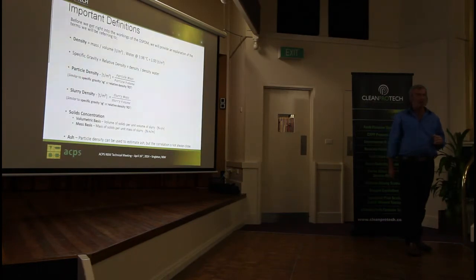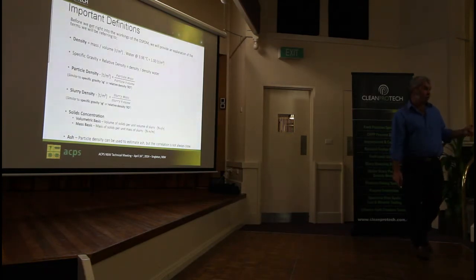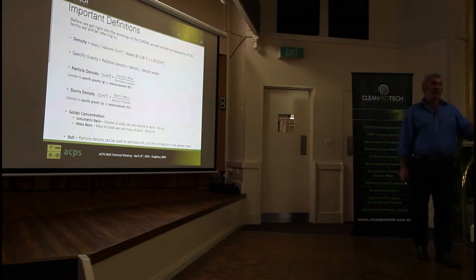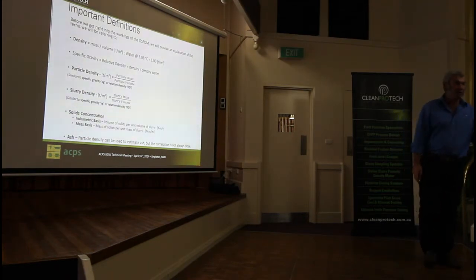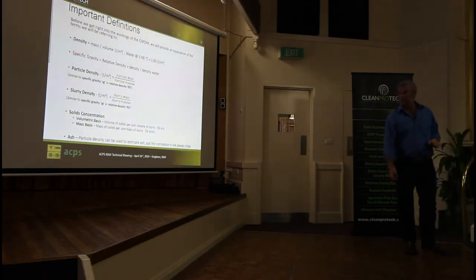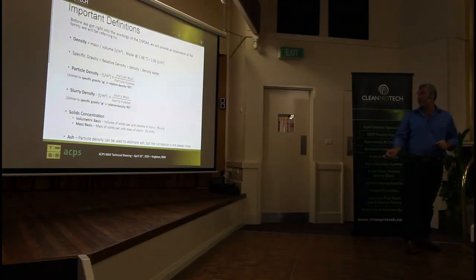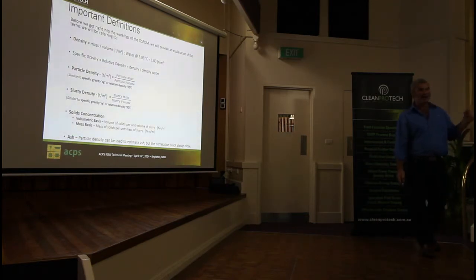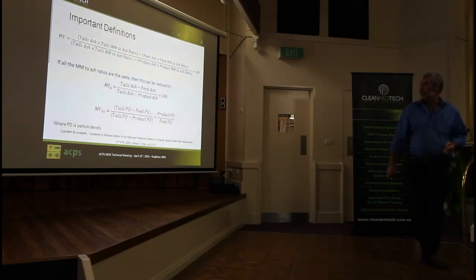And of course you've got solids concentration. Very important to remember with solids concentration, for percent solids, there are two different things, by mass and by volume. They're not the same and should not be confused in any way. Okay, ash and particle density, again, it's another story. Don't confuse them. It's interesting: particle density is a real term, ash is an artificial term. We've probably got to remember that about ash.